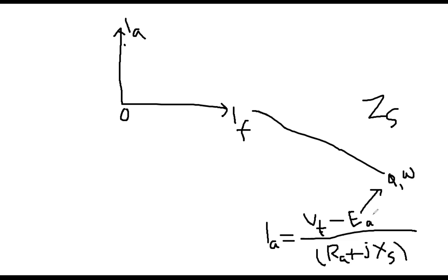And then the motor has started rotating, meaning that the back voltage has started to build up. Gradually this value is increasing with the increase of the flux. What is happening? Because it is subtracting, your I value is decreasing.